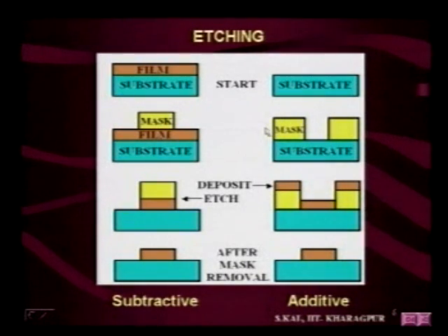Photoresist is coated, and using the mask it is exposed and developed and you get a pattern like this. Here the masked region is different from the earlier one. In the earlier one you masked the central region.